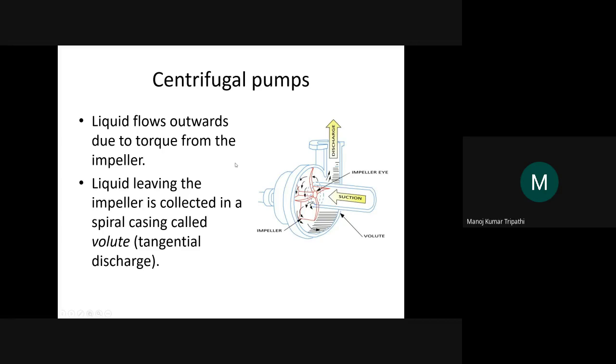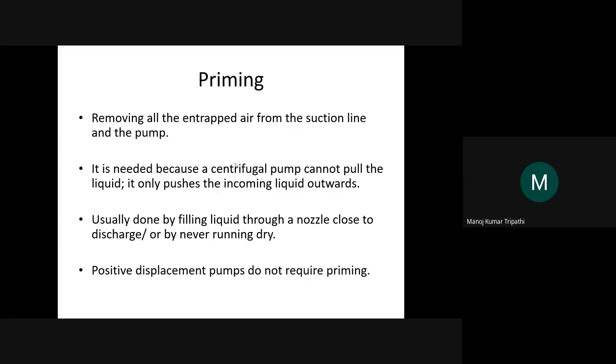So all of these different kinds of pumps, you have a wide variety of pumps. You might have heard about submersible pumps. So they are also centrifugal pumps. They are already dipped inside the water, so they don't require priming. That is already taken care of. But when you have a pump outside the water tank, that requires priming if it goes dry. So the solution is just to refill it, to fill the pump and the inlet pipe with water again, and it will run.